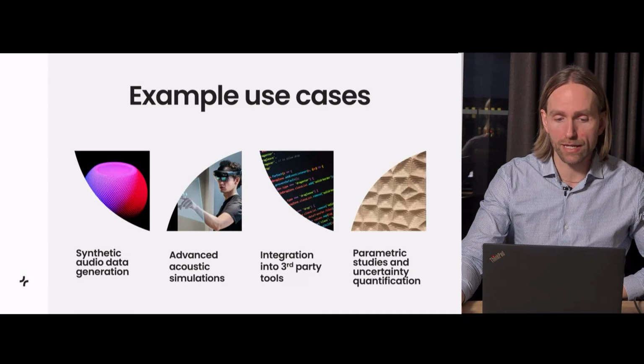Being able to run advanced acoustic simulations, such as full bandwidth wave-based simulations, ultra-high order ambisonics output, and there are some advanced features in the SDK which have not yet at least found their way to the simulation suite. Integrating it into third-party tools, as previously mentioned, and being able to do, for example, parametric sweeps, where you, let's say, automatically vary absorption in a room across some range, and then you have the whole thing simulated through the SDK and get back an optimal result or something like that.